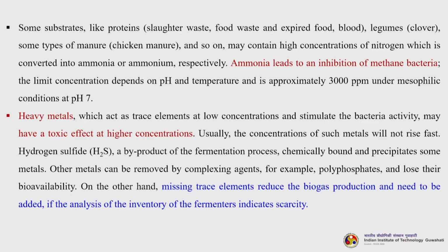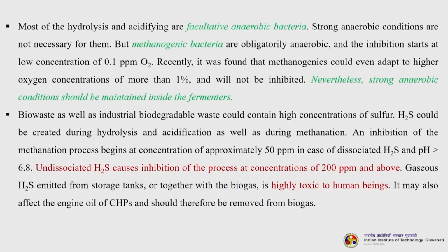On the other hand, missing trace elements reduce the biogas production, that is also an issue, and they need to be added if the analysis of the inventory of the fermenter indicates scarcity. You need to keep on monitoring every day, even on an hourly basis, so as to find out the heavy metal concentrations, then you will find out whether you need to supply them or they are already present in sufficient amount.